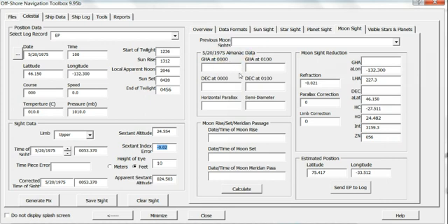The program has prompted me to enter the almanac data in this section. For the 20th of May, it wants the Greenwich hour angle at 0000 and at 0100, the declination at the same time, and then the horizontal parallax and semi-diameter for that date. So let's start. Going to the nautical almanac, I see that the Greenwich hour angle at 0000 is 68 degrees 55.6 minutes. At 0100 it's 83 degrees 24.8 minutes. The declination at 0000 is south 20.4 minutes, and at 0100 it's south 33.4 minutes. The horizontal parallax is 59.5 minutes, and the semi-diameter is 16.2 minutes.